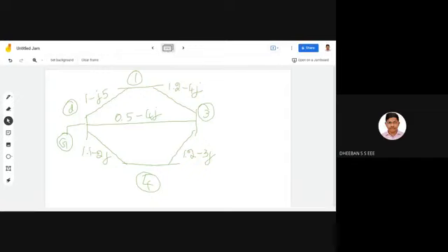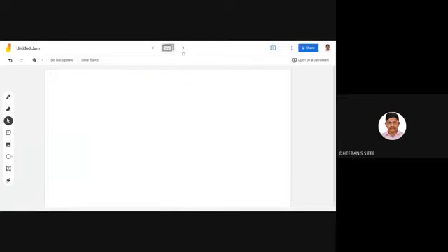They have given you the value of your admittance directly. If they are giving impedance, they will specifically mention it in the problem, saying the given value is in impedance. Otherwise, by default it is admittance only. So I hope you have taken down the single line diagram. I'll be moving on to the bus data.